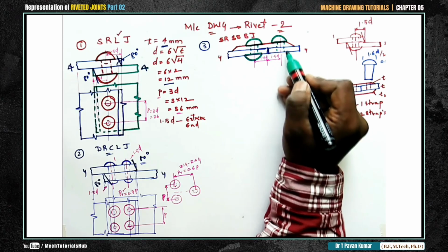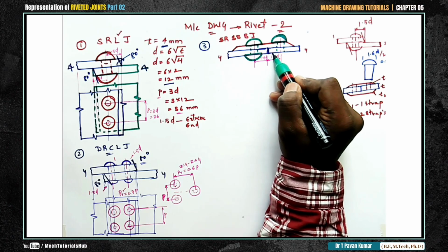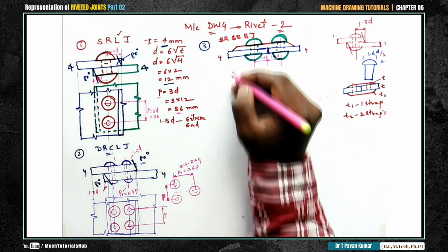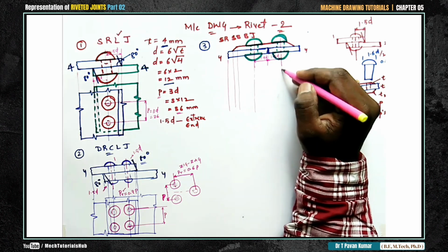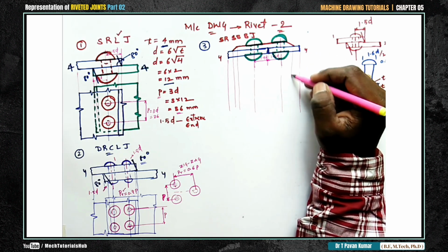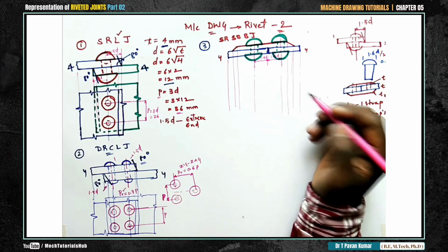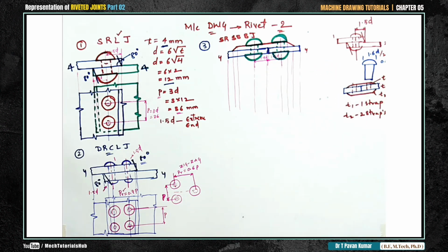This is similar. The only thing is we are changing the joint type. Other things will remain the same. This is how we'll do it. This is the front view. If you consider the top view, again draw the projection lines 1, 2, 3, center line, extreme end point, strap, sheet, the other end of the strap, all these things. You need to project many things, and the butt, wherever both the sheets got joined with each other.